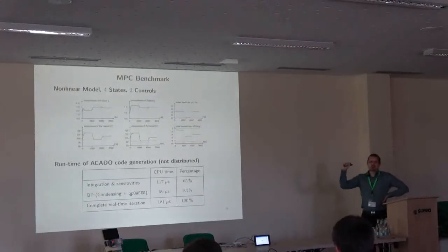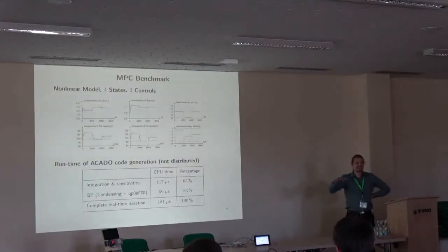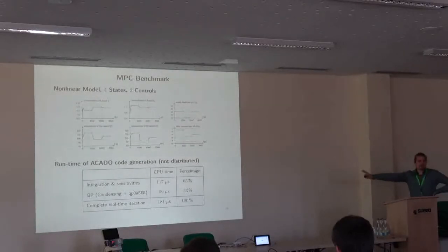But of course, the computation times are not that great anymore. If it's between 1 and 10 milliseconds, you would still be okay for most mechanical systems. But if it goes over that, of course, the sampling time starts to be prohibitive, right? So if we want to scale up a little bit further or do more complicated methods, we run into the limitations of MPC that Sigurd also mentioned. As soon as the models get more complex, like a big chemical network where we rather have thousands of states maybe, that could be troublesome.